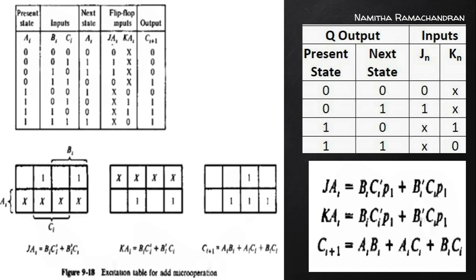After addition, A plus B, we also need to add the carry in value. That is, A equal to A plus B plus C in. Right? A equal to A plus B plus C in. After addition, the resultant value is placed back into our accumulator itself. So 0 plus 0 plus 0 is 0 itself with carry out equal to 0.